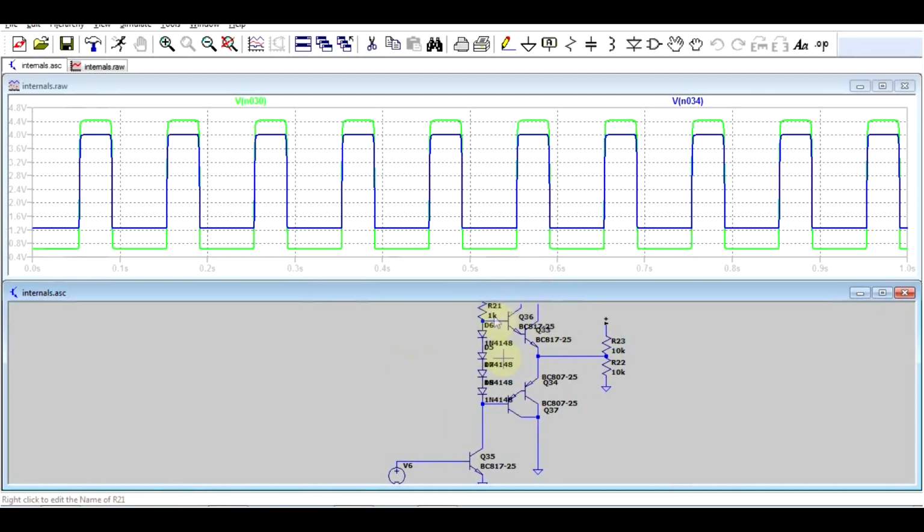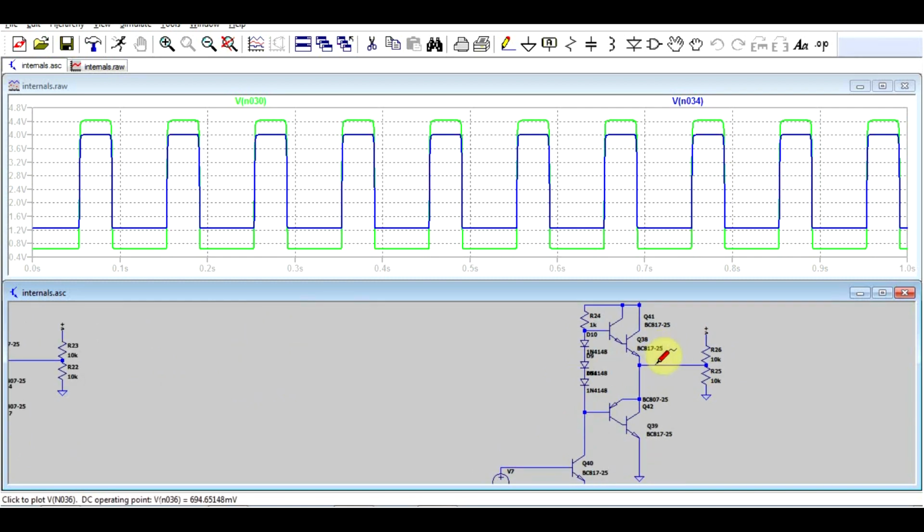Now we can have symmetrical limitations and we can have asymmetrical limitations. For example, with this stage, here we've got the 0.6 volt low side and the 1 volt high side limitation, even though we are using double transistors both on top and on the bottom. That's because on one side we've got two NPNs, on the other we've got a PNP and an NPN. So depending on how you're designing your output stage, you will have various limitations. So this is nice. We can see where we get our limitations. So how do we get rid of these limitations?